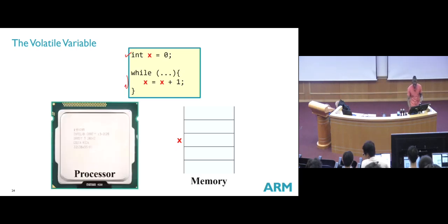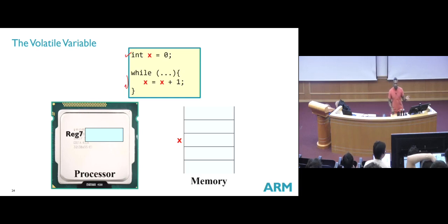And when I want to execute this code, at the assembly language level, the ARM is what you call a load store architecture. A load store architecture means that before I can do anything, I need to load. Load means I take the data from my memory, put it into my internal register, perform the computation, and then eventually I write back.